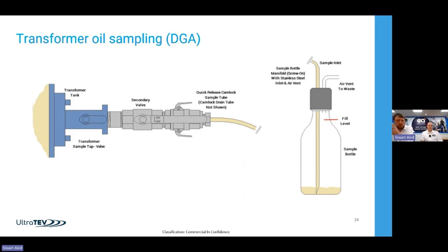It'll let you trend the age of the oil and the degradation of the transformer over time very well, and will give you plenty of time and headroom and some service options in terms of replacing the oil, refreshing the oil, which allow you to extend the lifetime of it. So if you're not doing DGA analysis, it's worth looking into. It's also worth looking at how you do your analysis.